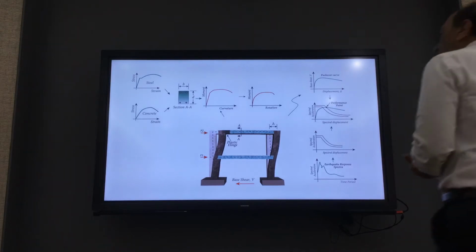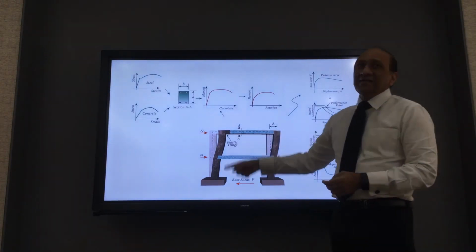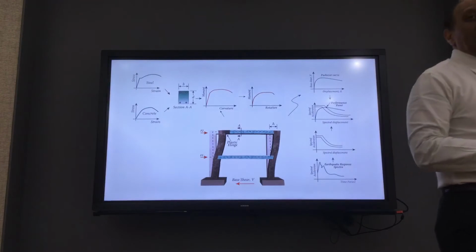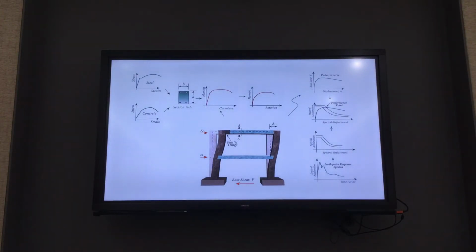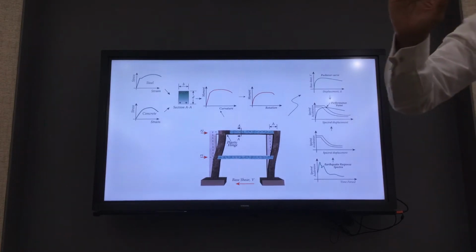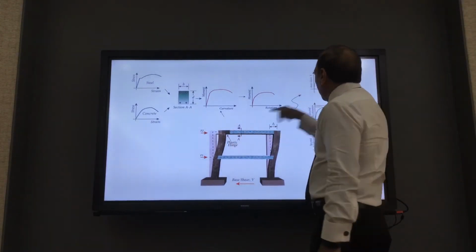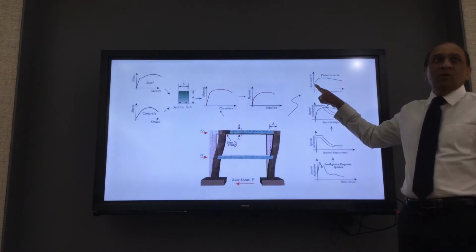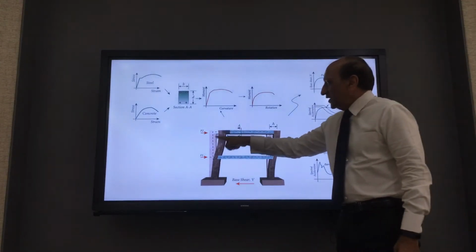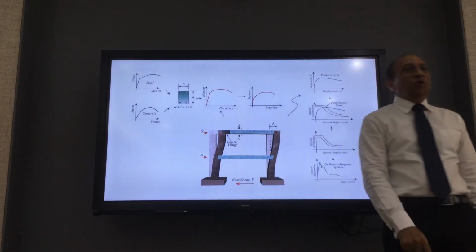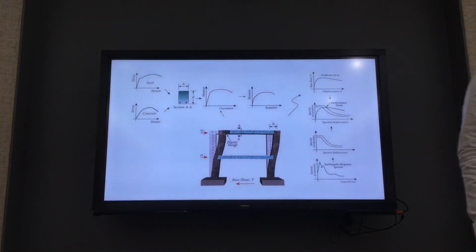Okay. Fault number one is that this is a static pushover method. That means it is based on response spectrum, not time history. So it cannot accommodate the varying ground motion changes. It is only giving you the performance for a given force pattern, which we applied here. If you change the force pattern, this curve will be different. Then performance will be a different pattern. So this is corresponding to a particular load pattern that you have to assume in the beginning.